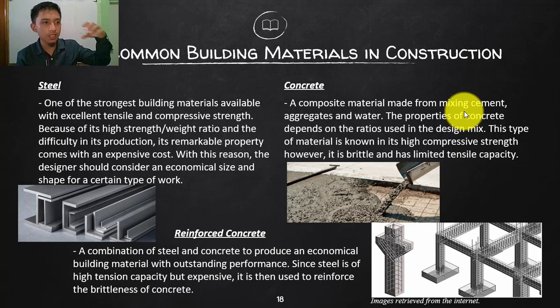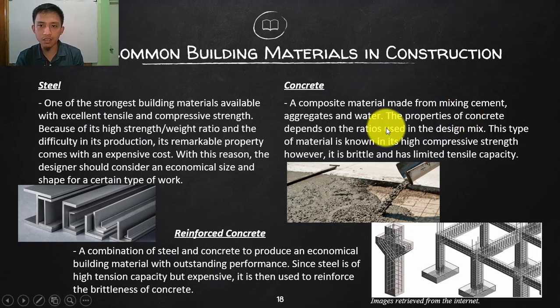Together with the cement, we are going to dissolve the cement into water so that the paste will act as a binding agent to the aggregate. If that cures, then that will be a solid material. So that is the concrete. The properties of concrete depend on the ratio used in the design mix. So actually the strength of that concrete is not fixed.